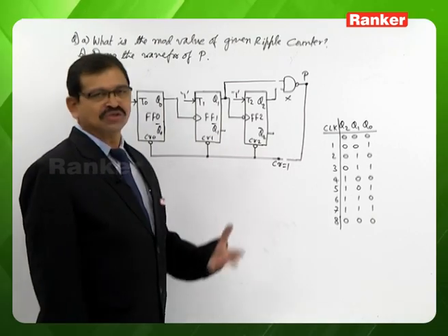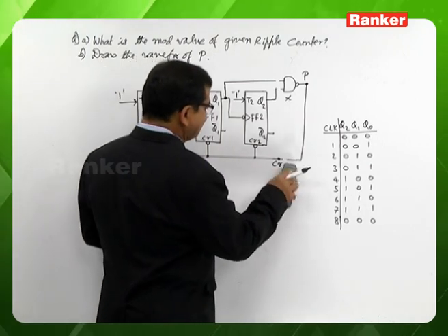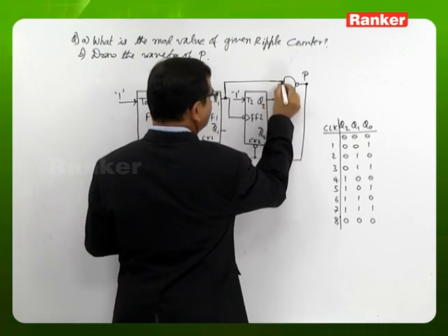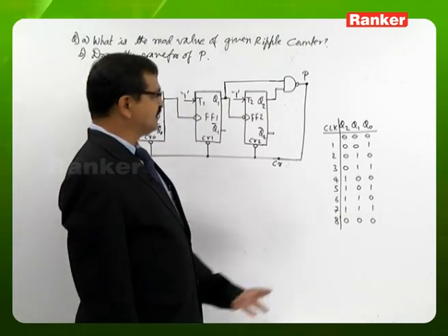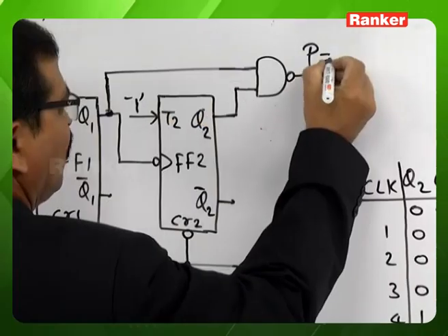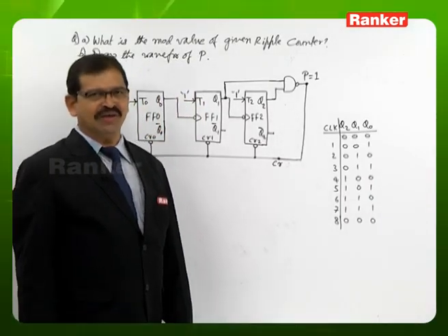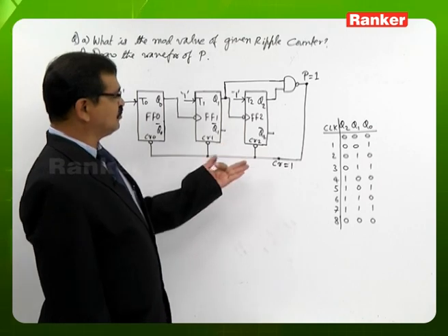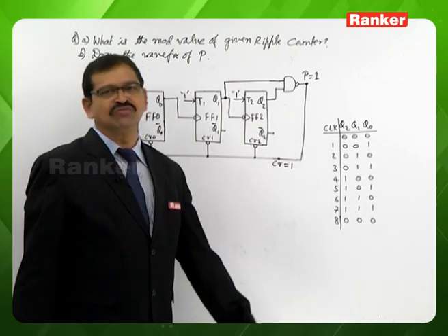Now in this question the problem is that the NAND gate output is coming as the clear input of all these flip-flops. Based on circuit 1's operation, it is possible to understand that as long as this NAND gate output is 1, the clear is connected to 1. Even now, the circuit operation is similar to the circuit 1 switching sequence. It must follow this switching sequence.